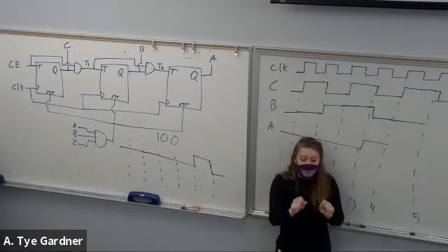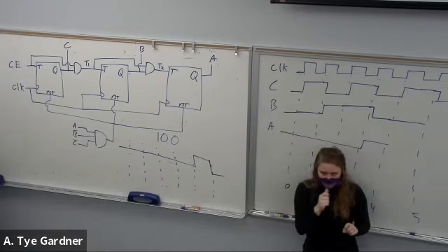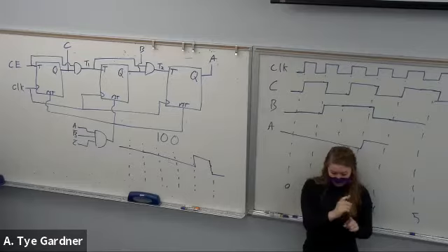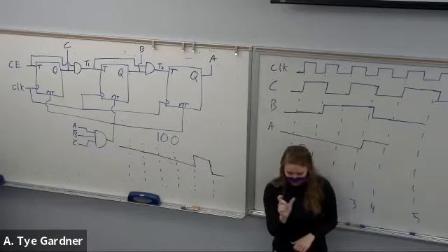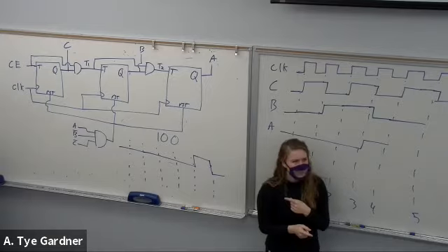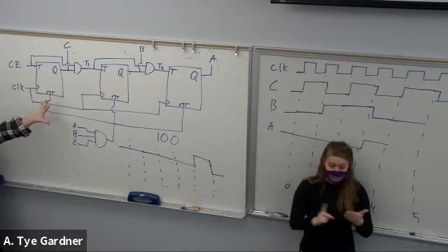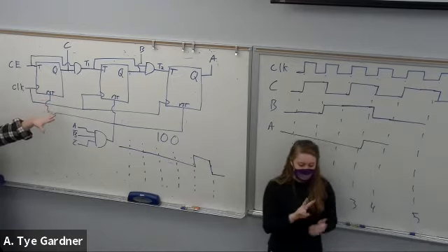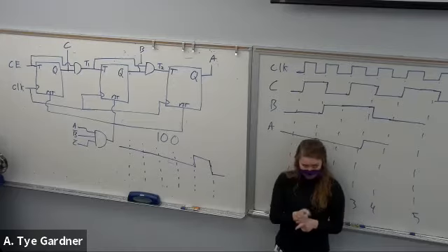Wouldn't you want to reset it on 1, 0, 1, not 1, 0, 0? The 1, 0, 0, that would be the 5th term. Wouldn't you want to reset on the 6th term? You might be right. I'd have to go back and think about this sometimes because I don't usually design them directly this way. There's some VHDL that I'll show you that is actually how we do it. This is kind of the circuit way. You might be right on the 6th term.